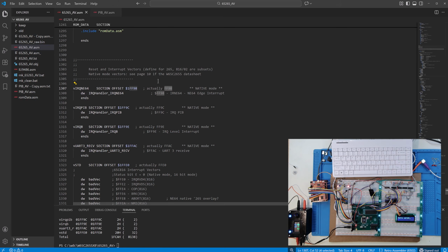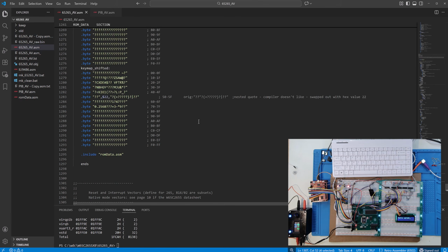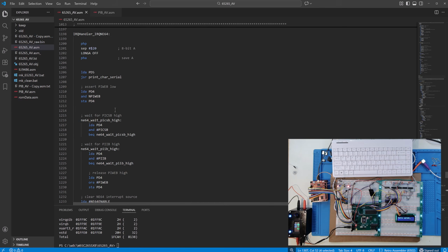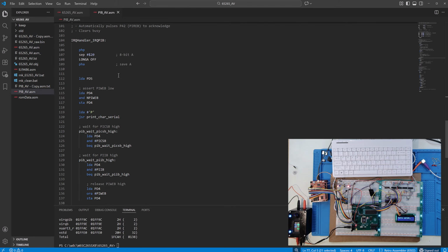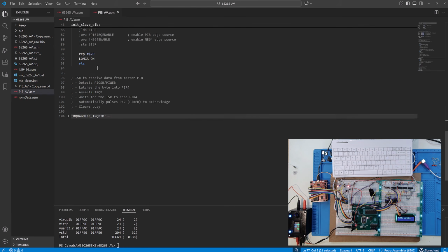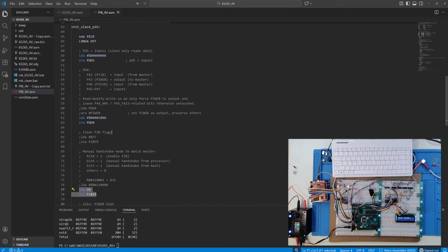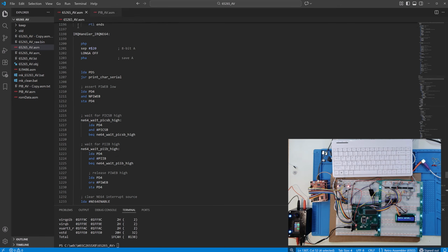But then I have that handler set up, and I think I left that here in my main right here. Yes. So that's this interrupt. I'll come right back to that. So ignore this one. I'm not using this one. And it's really just the setup, the init here. And then at that point, it goes back to its normal processing, looping in the main, whatever. But when the master drops that first signal for the interrupt, then this interrupt handler is going to run.